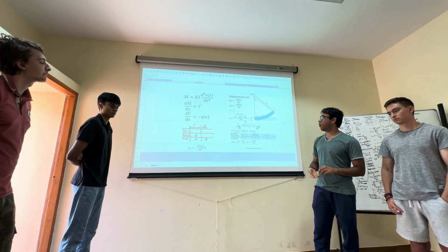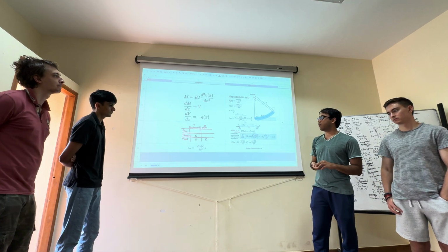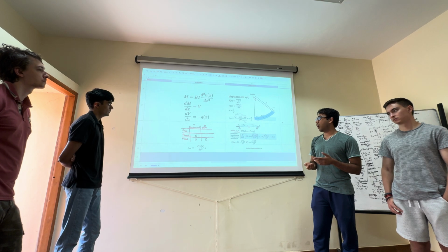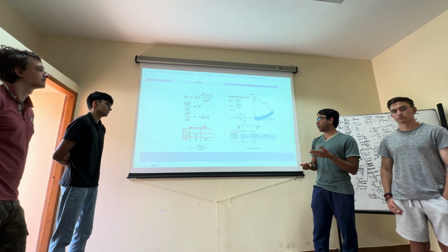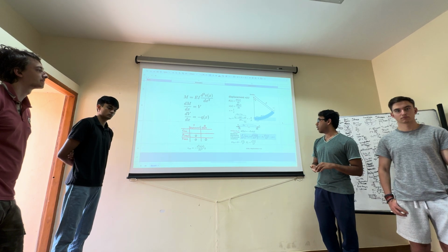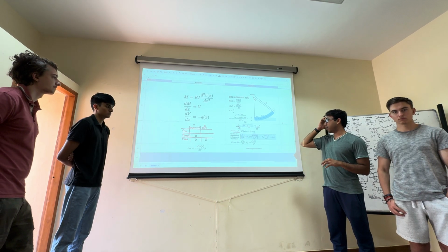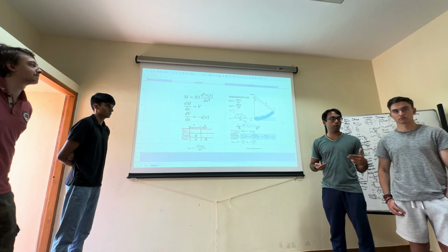And furthermore, we have both the two equations that show that taking an integral of shear force will give us the moment, taking the integral of the loading condition will give us the shear force. And one more thing that I added was an example of buckling due to an axial force being applied.